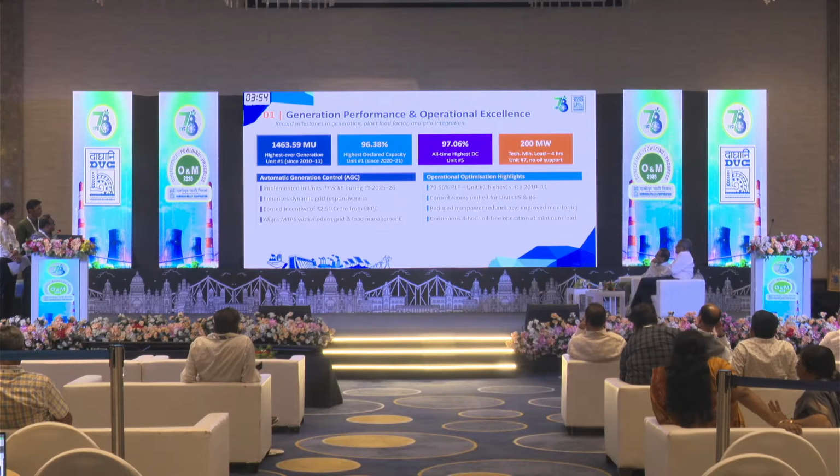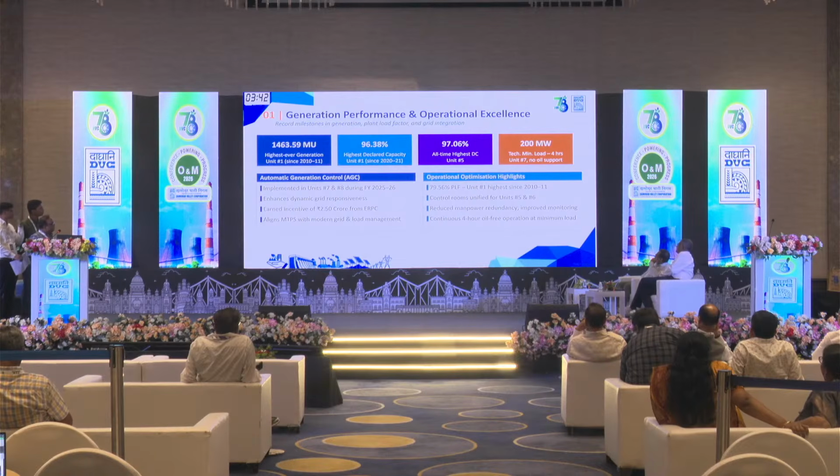The highest declared capacity is 96.38% since 2020-21, and the all-time highest is Unit 5, 250 megawatt, at 97.06%. The most challenging part is the 40% capacity in 500 megawatt, with minimum load of 200 megawatt, running within 4 hours without oil support.